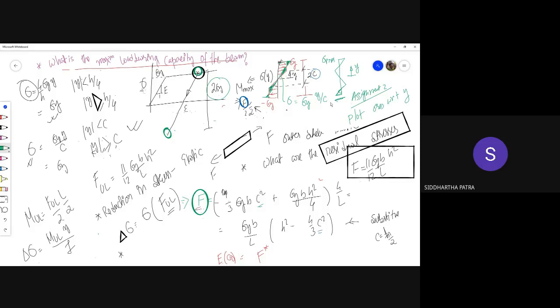So that's why we say, when a material has been forged, when we do forging, it develops compressive residual stress. And actually you may have heard that when there is a welded joint, at the welding, to make it stronger against crack propagation, okay, crack propagation is the problem of tensile loading. Compressive loading does not cause crack propagation. So what do people do? They hammer the welded joint, or fire hardened metallic balls at the welded joint to incorporate residual compressive stress.